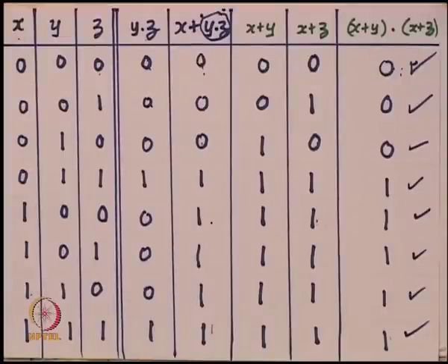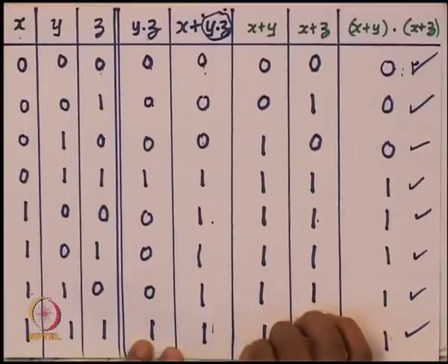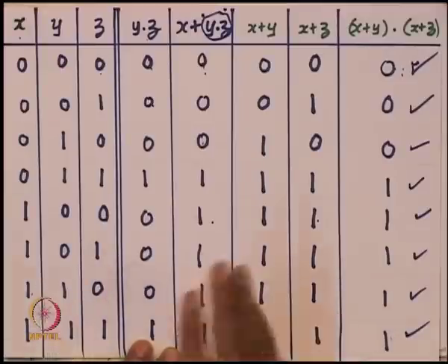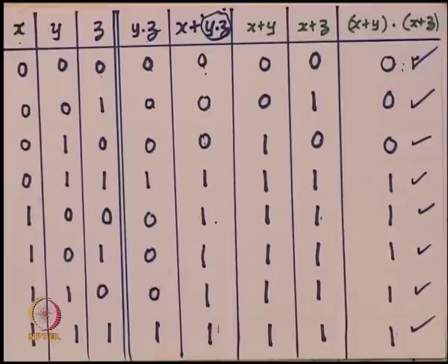So this is such a basic proof technique that you need to know, and if not for anything, you can always go back to what is called drawing the truth table to get the correctness. If I want you to show that something is equal to something, you can always go to the LHS, get a truth table for it, go to the RHS, get a truth table for it, and show that these two columns are equal. This will work well if you have very few inputs. This may not work well for bigger number of inputs or for other functions, but at least there is a fallback option, a safe option that you can always resort to if you do not have any other technique to solve this problem. So we will see more of these 3 variable theorems and so on as we go.